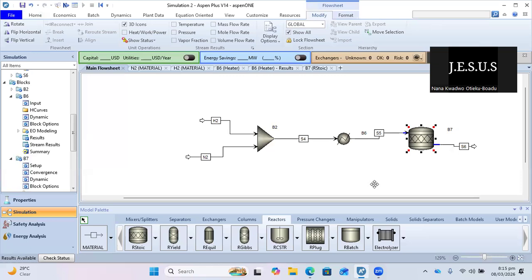Sorry. Okay, if we say a reaction is in series, what we are saying is that when the first reaction happens, the second reaction follows after it. They don't happen at the same time. So maybe your first reaction happens, then the product of the first reaction might now react to form something else. So that's in series. If it's in parallel, they're happening at the same time.